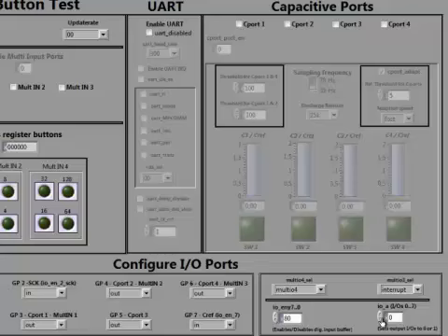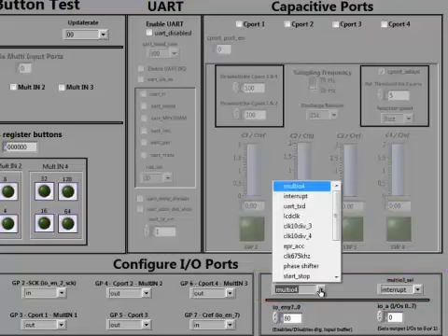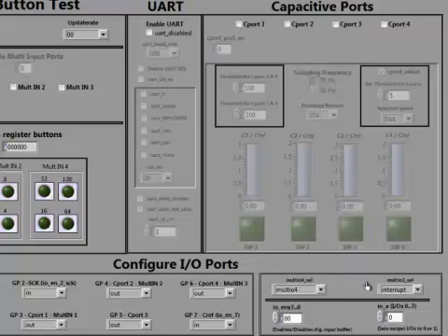There are 2 I/O pins in the PS09 used for diagnostic functions, namely GPIO 3 and 4. The various possible diagnostic functions on GPIO 4 can be selected from this drop-down box here. For example, selecting UART-TXD will map the transmit output of the UART module in the PS09 onto the GPIO 4 pin. Please remember that you have to additionally configure the pin itself as input or output depending on the diagnostic function you choose. This box is similarly for selecting the functionalities on GPIO 3.